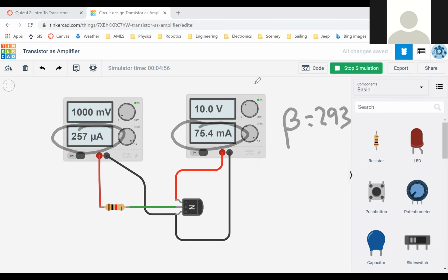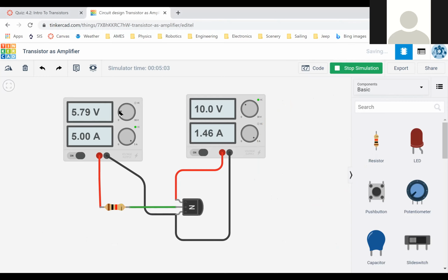What if I had chosen a different setting? What if I had gone up higher to a setting like this? Now I've got a whole different set of numbers. So I'm going to do 1.46. Notice that's amps now, not milliamps, so I don't need times 10 to anything. Divided by 4.98, and that's milli, so that's times 10 to the negative 3.